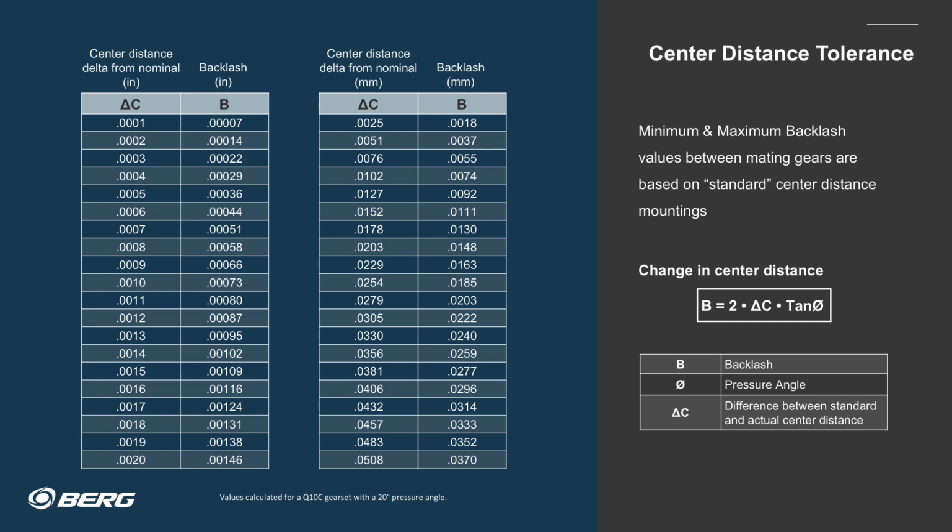This is why, most often, the Berg engineering team works to evaluate a gear system instead of increasing gear quality. Many other parameters influence backlash and need to be addressed differently. If the center distance tolerance is too wide, no higher quality gear will resolve the backlash issue.